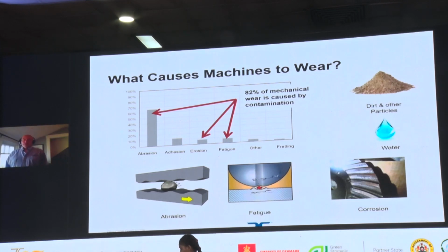In gearboxes that we see in wind turbine applications, fatigue is one of the leading causes of bearing failure in wind turbine gearboxes. In addition to particle contamination, the other contaminant that we are concerned about is water, and that's particularly prevalent in wind turbine applications because a lot of our installations are in coastal locations, right? So that's obviously where the prevalent winds are, and of course, being close to an ocean means that the ambient humidity in the nacelle up tower is going to be pretty high.